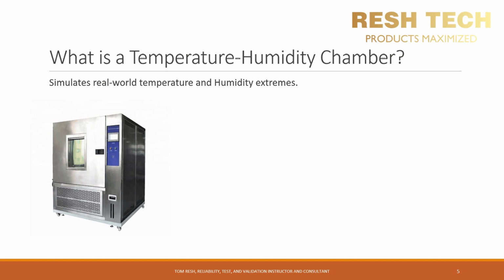What is a temperature humidity chamber? A temperature humidity chamber simulates both humid, which is humidification, and arid climates, which is dehumidification. As you can see, the chamber in the bottom left-hand part of the screen is very similar in outward appearance to a temperature test chamber. The key difference is the components included internally in a temperature humidity chamber, which will have options such as a steam generator for humidification and a dehumidification coil, think small evaporator coil circuit, for low humidity conditions.